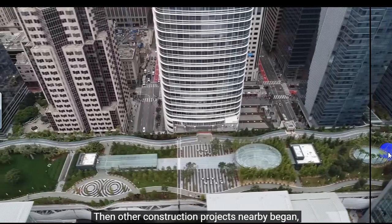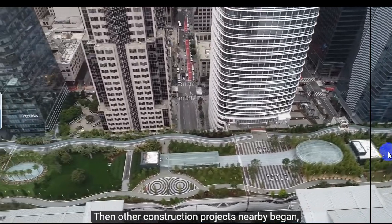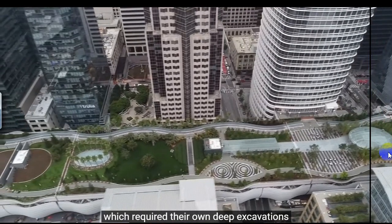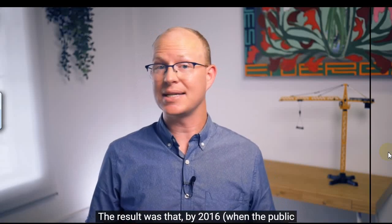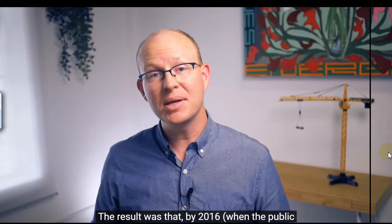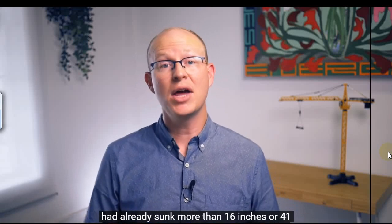Then other construction projects nearby began, including the adjacent Transbay Transit Center, which required their own deep excavations and groundwater drawdowns. All these factors added up to a lot more settlement than was initially anticipated by the project's geotechnical engineers. The result was that by 2016, when the public first learned about the issue, the building had already sunk more than 16 inches or 41 centimeters, triple the movement that was anticipated for its entire lifetime.